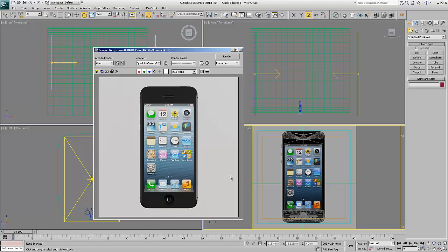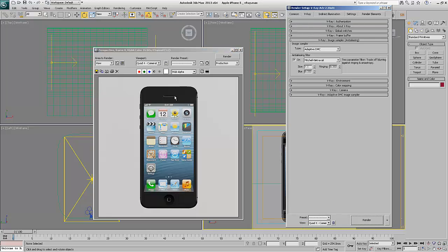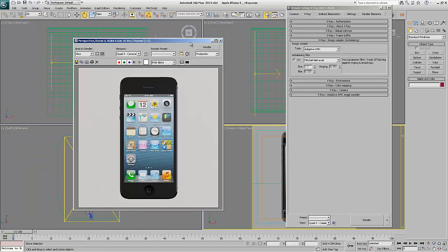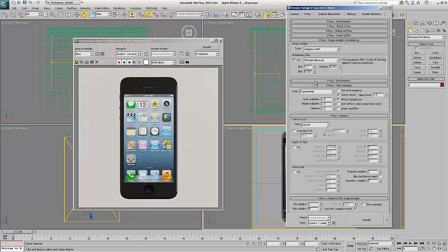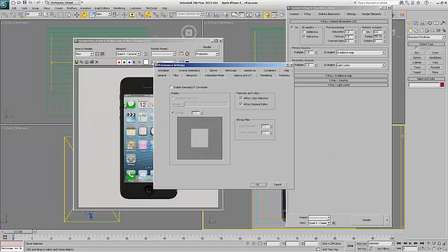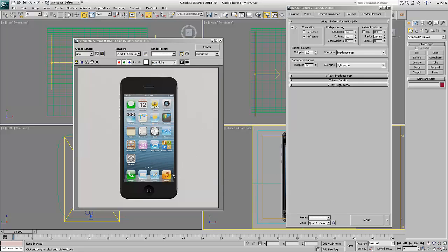Now, I did a render. This is the file literally from TurboSquid opened up and looked at in Max. And for my taste, this isn't really the setup I can go with. While he is using V-Ray lights, he's not using a V-Ray camera. And anybody who's watched my stuff knows that I don't set things up this way. I use a different method. He also has his gamma control turned off. So for me, even though that looks cool, I like to work inside my own settings so that I can anticipate what things are going to look like. So this is all good.